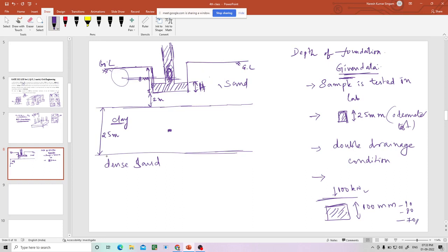Let us say height, the settlement. Now what is the settlement? 30 mm, because the height has reached 70. This final settlement is called primary settlement of the soil sample. Now even if you keep that load for some more days or years, the settlement will not increase. The final settlement is 30. People call that 30 mm the consolidation settlement.